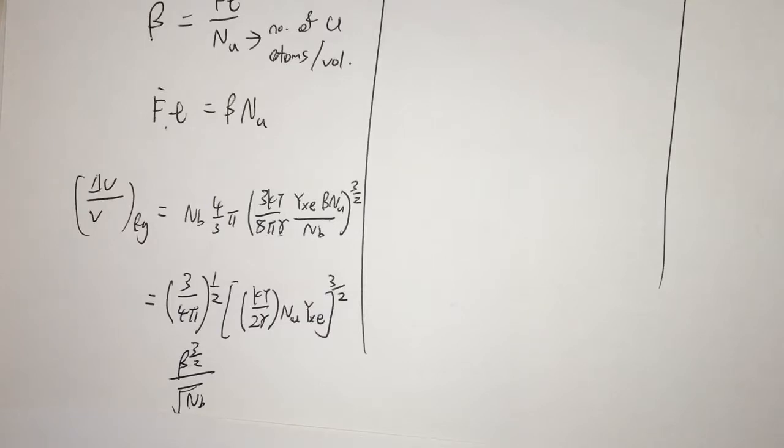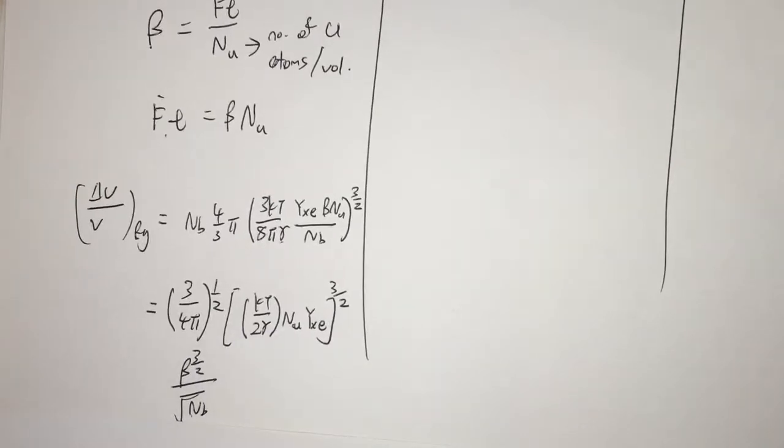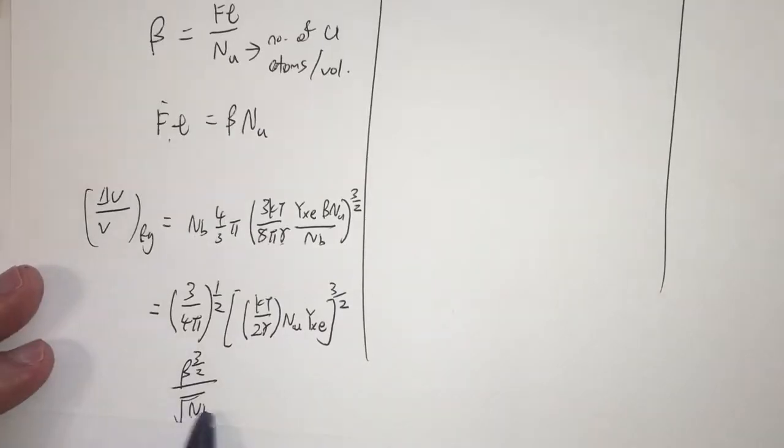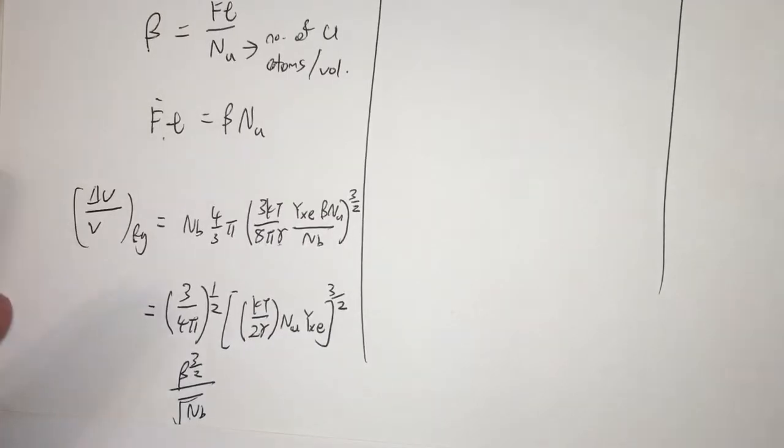We can see that our expression still requires knowledge of the bubble density, and the rest have been discussed before. While we may not exactly know what the bubble density is, we can still plot swelling as a function of burn-up, so that we can find some upper limit, except that we plot a family of curves for different bubble densities.